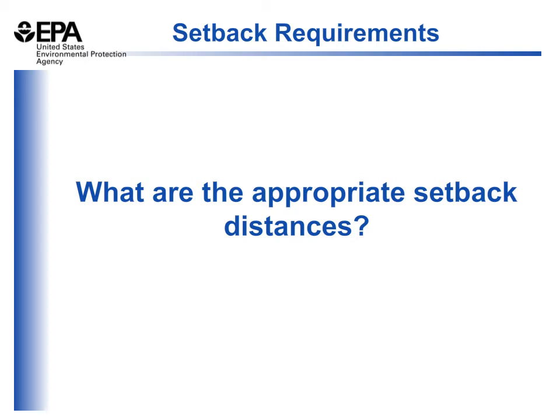As you think about this, what are appropriate setbacks to some of these environmentally sensitive areas? For instance, what is an appropriate setback between a septic tank and a surface water? How about a septic tank and a water supply line, or a septic tank and a property line?